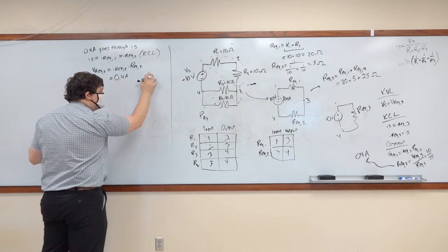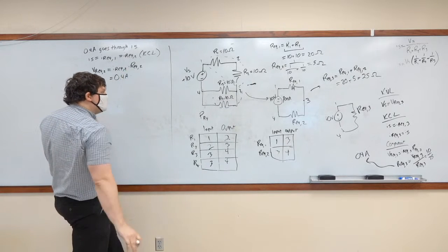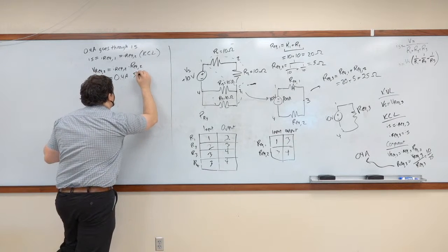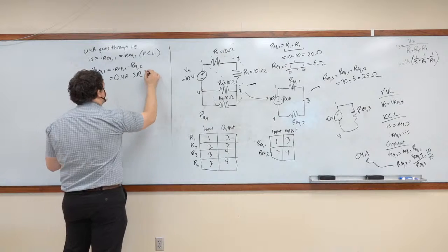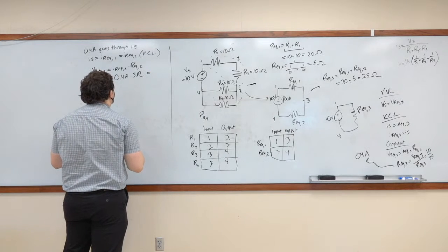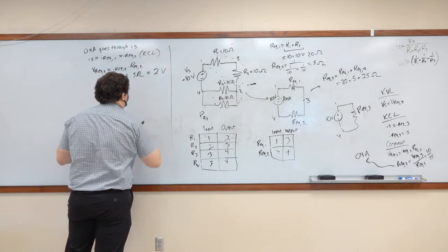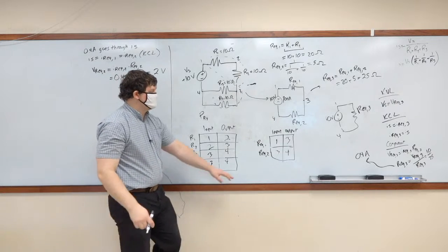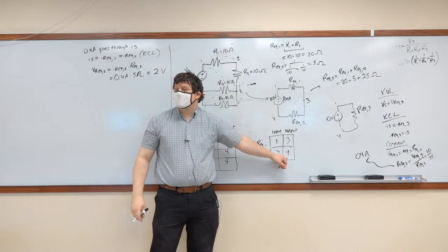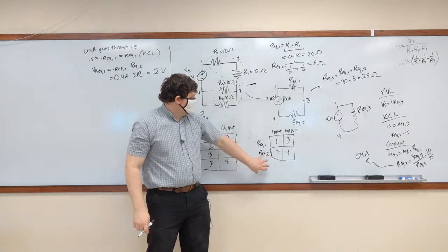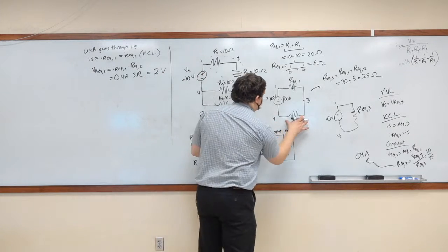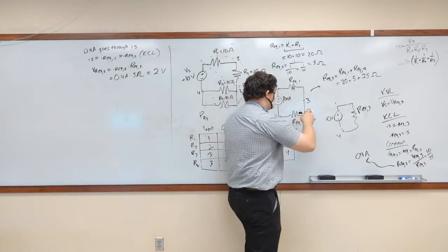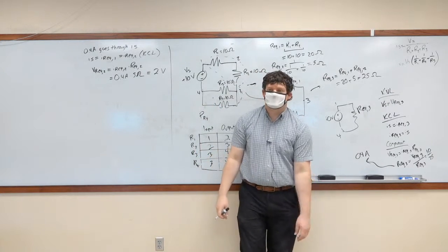We know that this is equal to 5 ohms, which means that the VREQ2 is equal to 2 volts. There are 2 volts between nodes 3 and 4. The equivalent resistance would experience a 2 volt difference. When we take those 2 resistors and we combine them into one, there are 2 volts across the ends.